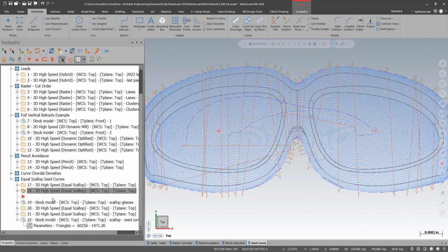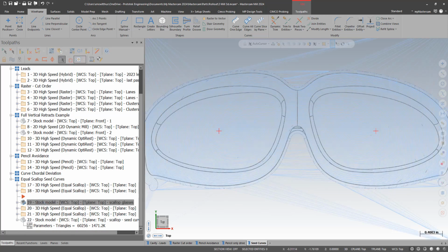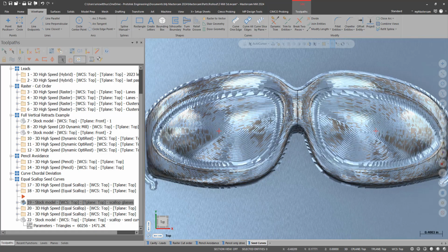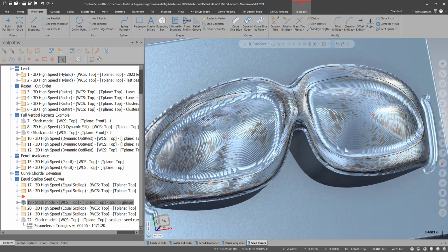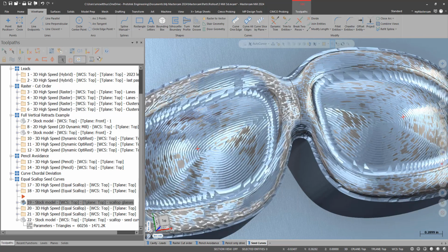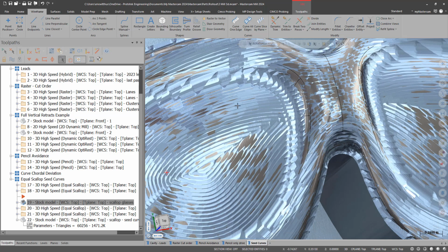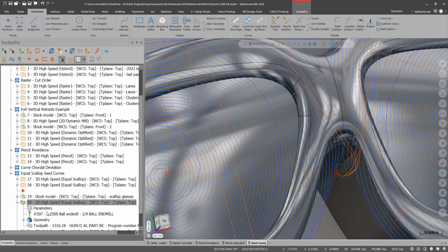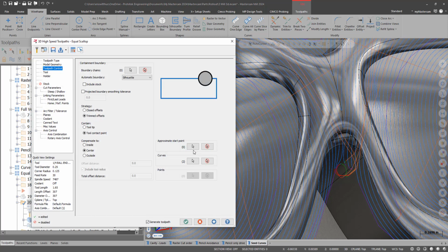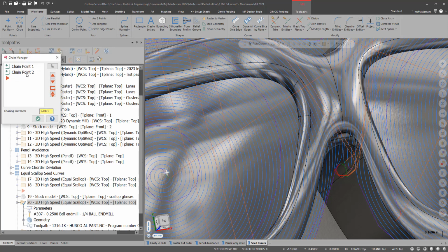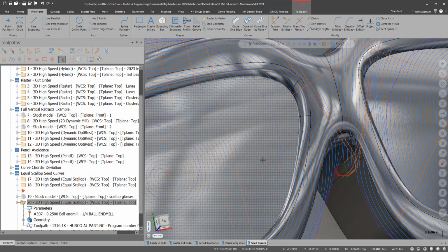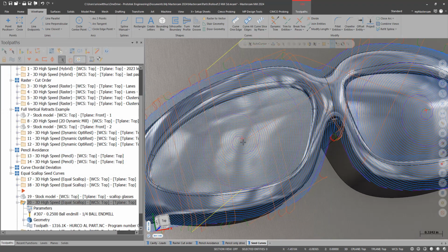And then what I can also do with scallop, once again, here I just made a stock model of the trimmed offset one. I end up with cusps in the corners, so I'm talking pencil would be great on that. Or I would prefer to cut kind of following that shape more to begin with instead of just running into them corners. So that's where I can start introducing seed curves. So this is what's new in 24, I can do points as seed curves. So this is what it looks like if I had points as seed curves. It kind of influences to that point.